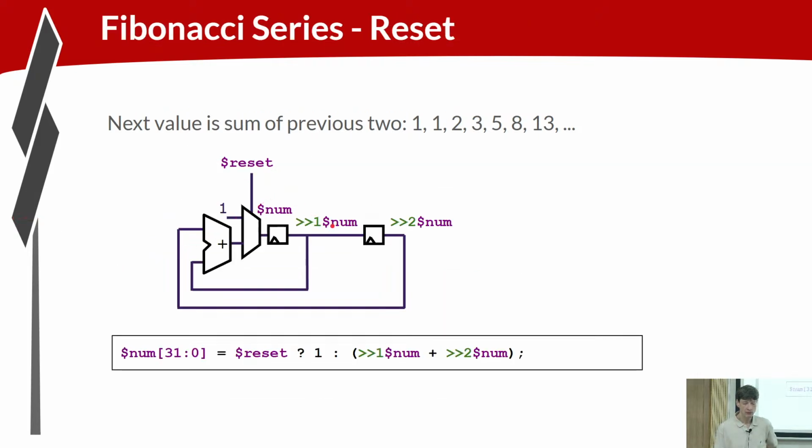And we can get 1 here and here by injecting a reset value of 1 in number, right? And then, as I said before, we rely on the clock, which will be running during reset, to propagate that 1 forward. So after reset, we're going to have a 1 here, here, and here. Importantly, we have a 1 here and a 1 here. And then we deassert reset, those 1s get added and become a 2, and the circuit continues. Make sense?